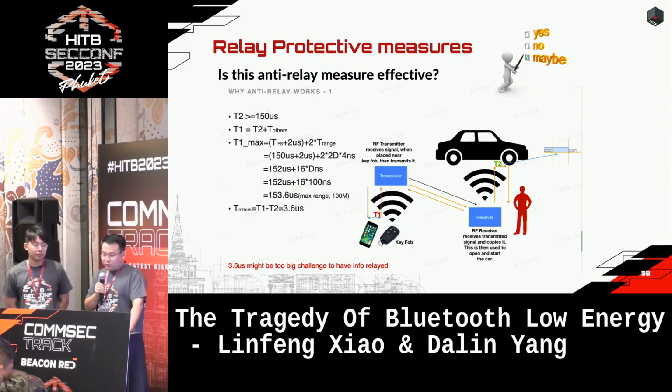The following is the NXP anti-Bluetooth relay method. Whether it's effective against traditional relay attacks, there is no doubt that the method has reduced the transmission time of inactive data over the air to 3.6 microseconds, which has made traditional relay unable to complete the data exchange. However, BLE link layer relay is different from the traditional mode in that both partners establish a complete link layer connection.